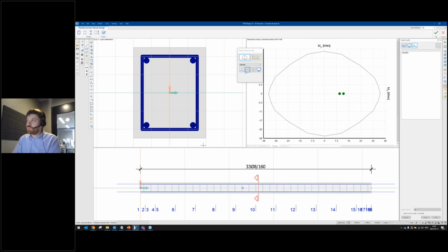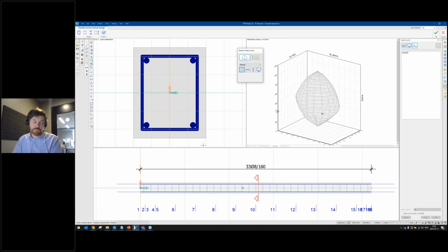So it's a useful tool to find these kind of issues, because you often think that a lot of load in the model is on the conservative side, but in this case, it's not necessarily conservative to add a lot of load in the model, since it could generate a big normal force in the object, which then in turn is beneficial for the moment capacity of that object. So I hope you're following along on my train of thought there. All right.